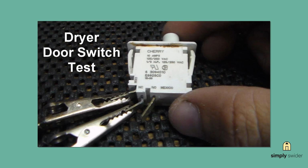Here's my go-to diagnostic test. First, make sure the dryer is plugged in but not running. Close the door normally and try to start a cycle. If nothing happens, close the door again and apply firm pressure directly on the latch area while pressing start. If the dryer suddenly starts working with that extra pressure, you've confirmed either a worn door switch or alignment issue.